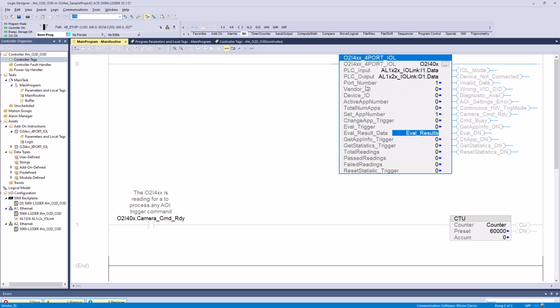Lastly, you'll need to input the port number. I am on port number 1 as shown in Mineo Configure earlier. So this could be for 4-port IO-Link masters, a value of 1 through 4, and of course for 8 ports, 1 through 8.